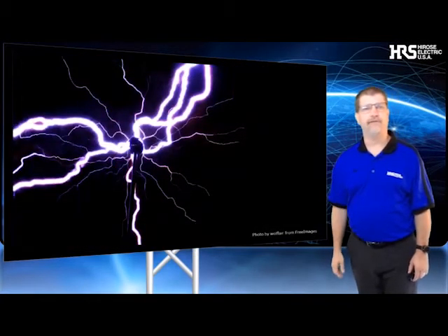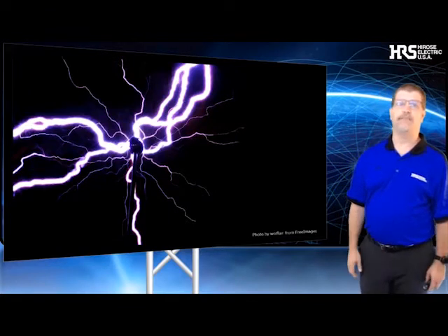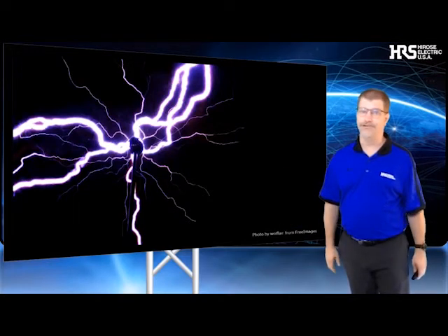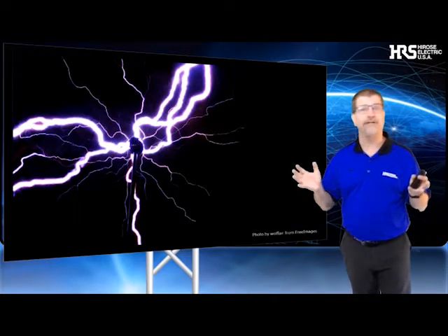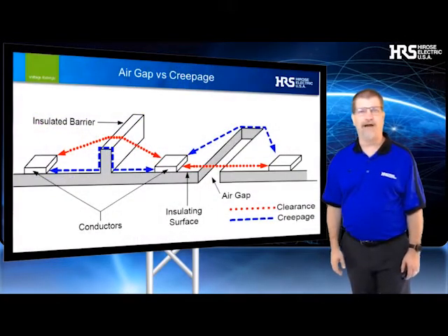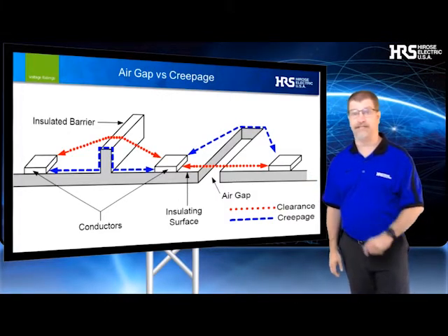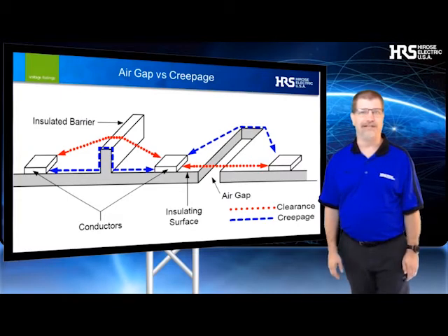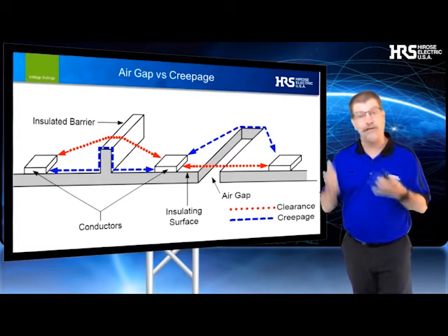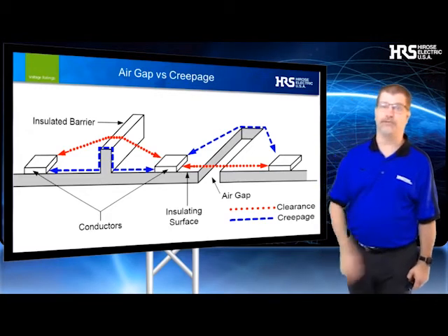Now let's talk about a few of the other design considerations, starting with the voltage. Voltage ratings seldom come up as an issue on power connectors, since typically when the voltage gets higher, the current ratings are also higher, resulting in a physically bigger connector, and hence a higher voltage rating. The two key values in a power connector when determining voltage are the air gap between the contacts and the creepage distance. We like to ask what the voltage is and make sure it is within the ratings of the existing target family that we've been working with based on the previous current discussion. Honestly, I seldom have issues here, especially with the Hirose connectors.